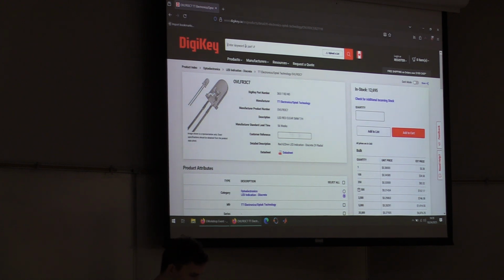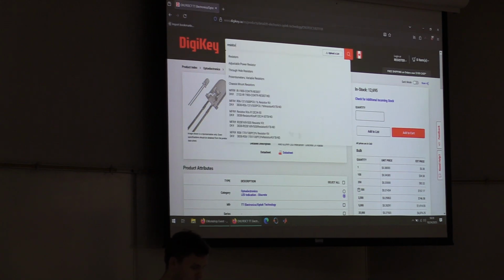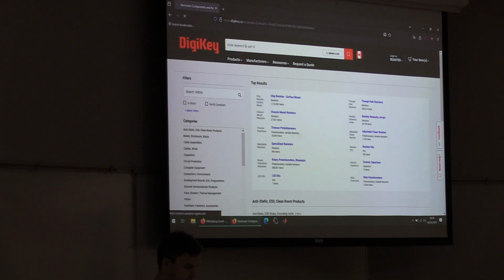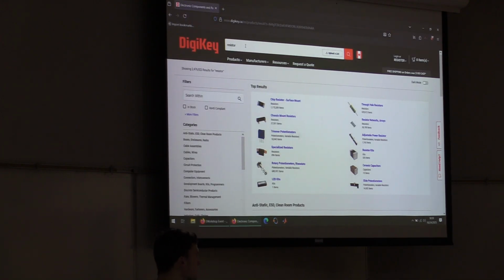But to start, resistors, you can find a lot of components just by typing in what you want. So if I type resistor, and I'll hit enter. Now we're given this selection. Now, what are each of these things? Usually they'll describe it. A chip resistor is a surface mount resistor. Or you can get through hole, which is what we're using in our schematic. You can get arrays, you can get a bunch of stuff. They even have capacitors for whatever reason in the resistors dialog.